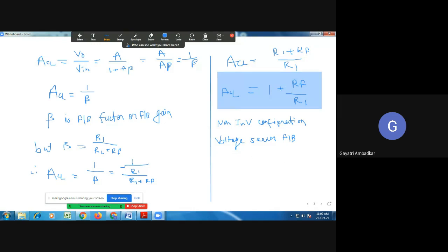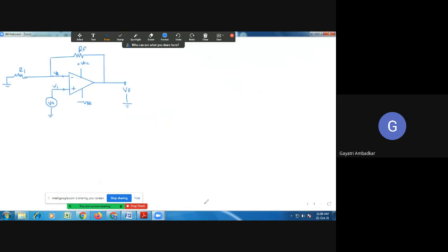Okay. So remember, now what I am doing. Op-amp, yesterday we have seen the current drawn by op-amp, we indicate it as IB1 and IB2. So let's say this is IB2 and this is IB1. And op-amp ideally draws zero current. So IB1 equal to IB2 equal to 0. Op-amp does not draw ideally any current, practically very, very small negligible current.